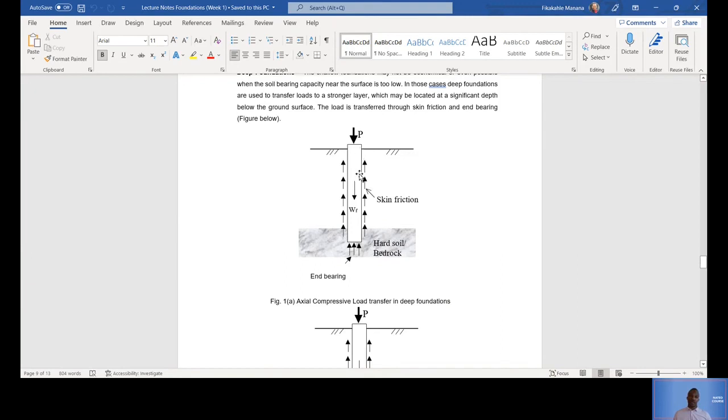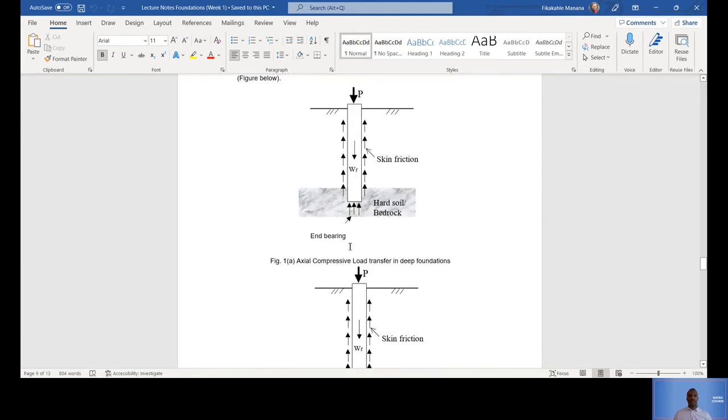In fact, you then put a pile that is as long as until it reaches a hard rock on that particular site, because remember the sandy soil will be the top soil, and then as you go deeper it becomes harder and harder, and when you reach a hard rock, bedrock, then that's how deep your pile will be. Okay, there you go.